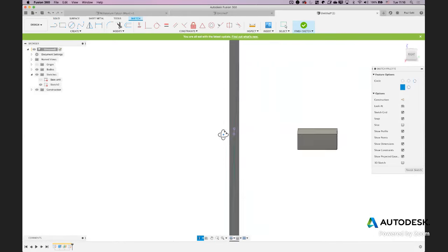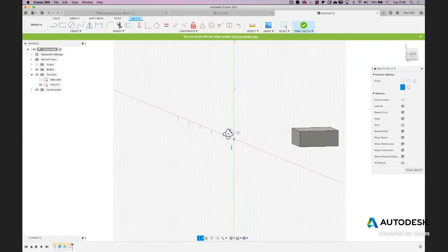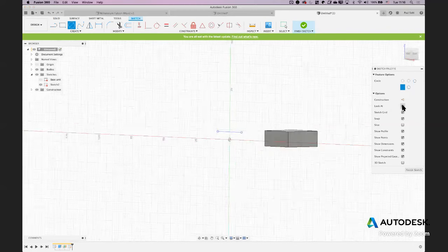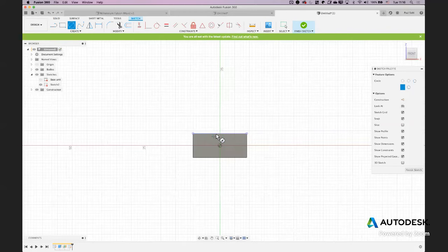So you can see the grid is offset from the surface because that's where that construction plane is that I told it that I want to do the sketch from. So I'm just going to hit this little look at button, which will snap me back to my 2D view. And then I can hover over my midpoint. You'll see that little triangle there denotes that I'm at the midpoint. And if I just pull this down, I can get to that position there. You can see it snaps to it. So it's 16.14. That's the first piece of my 1/4" jack.